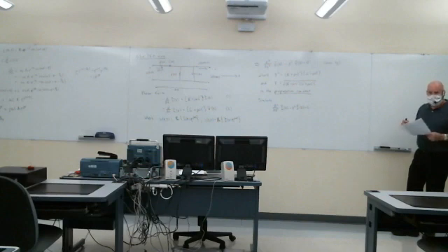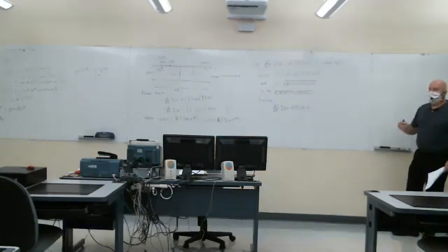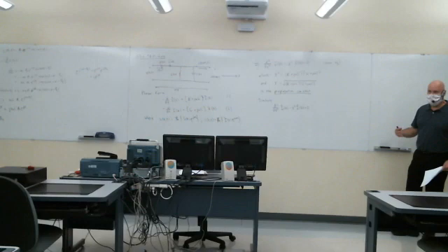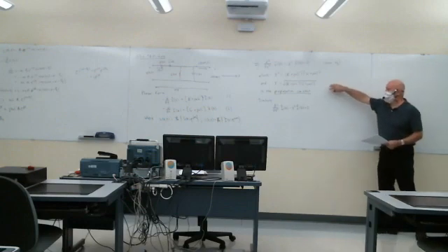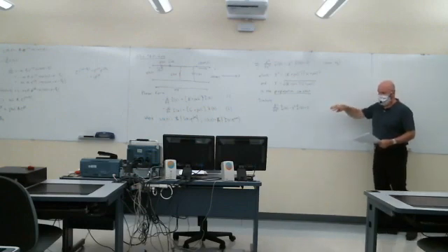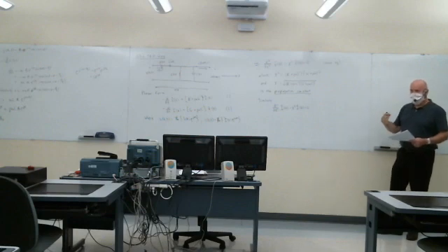But that means they can have different amplitudes. Remember, they're phasors, so back in the time domain they correspond to sine waves. They'll have different amplitudes and can have different phase angles. We'll also see, because gamma here is typically complex, that in the general case they're attenuated sine waves.